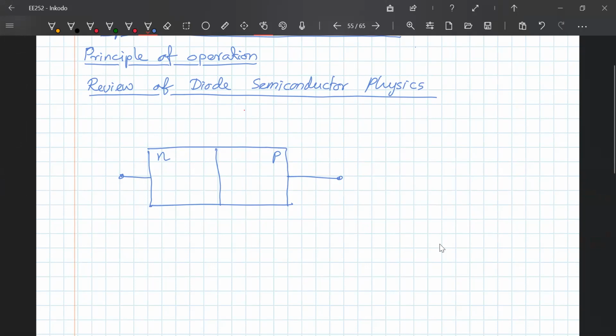So is germanium. But when you add a dopant, in other words an impurity, from either the third or the fifth column of the periodic table, let's say a little bit of aluminum, which is in the third column, or something like phosphorus, which is in the fifth column, there will be a few atoms where you have one more electron, in the case of a fifth column type like phosphorus, or you will have a lack of electron to bind with the neighboring silicon.